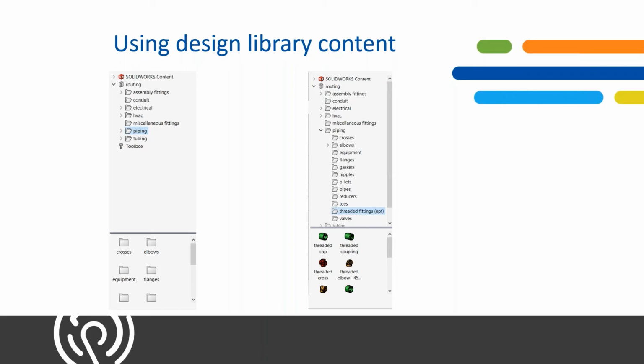And you can drag and drop some of those components. Once those components are put into your design library from your routing component wizard, each one of those components are going to give you a confirmation at the end to let you know that they've been saved into the correct location. Okay, so that is very important to do because you want to make sure that you saved out your component and saved out all your hard work, and you can go back and reuse some of those components. And I would save those to your design library, whether that is on your local machine or whether that's mapped from your Vault. But you want to have the file structure from the parent to child, okay, in that structure.